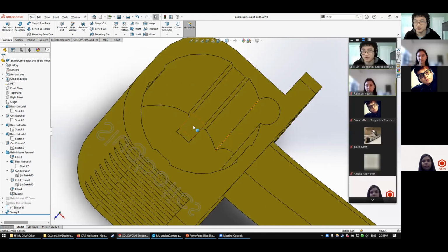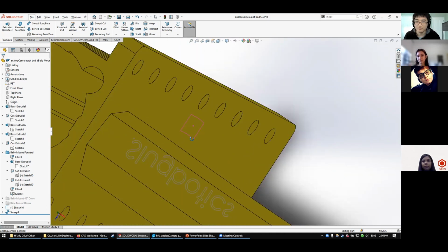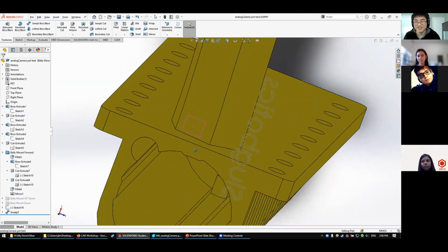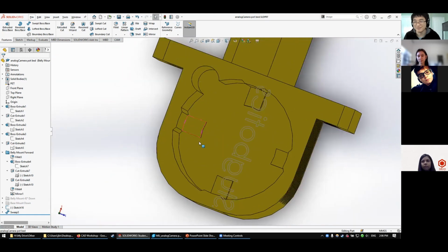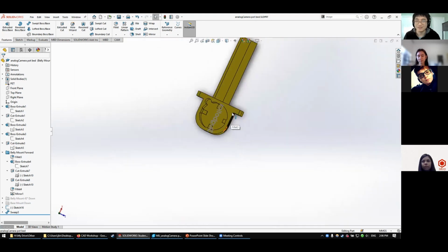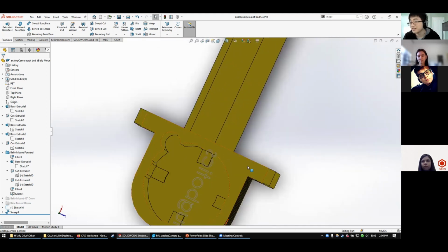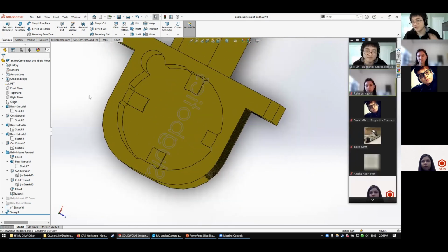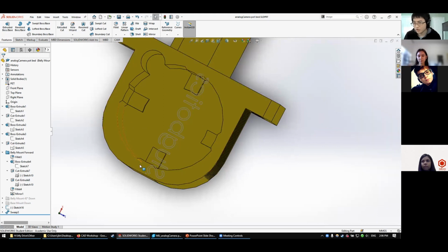Of course, you can always just do the middle mouse, shake things around, and eventually rotate your camera. So now we are upside down, but try not to do this too much because it gives you motion sickness. At least it does for me. So try to use Alt to roll the camera when it does work. It's not working for me that much because I think I have something way off screen, which is messing up the rotation. There, Control, Shift, and Alt plus the middle mouse let you get around real quickly.